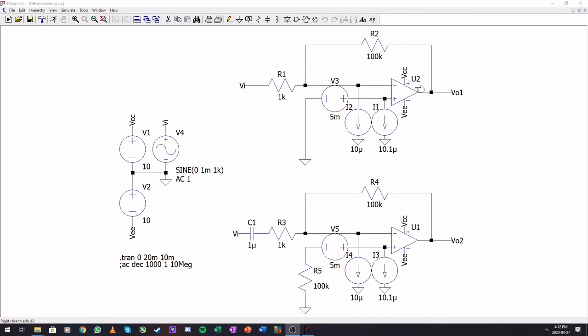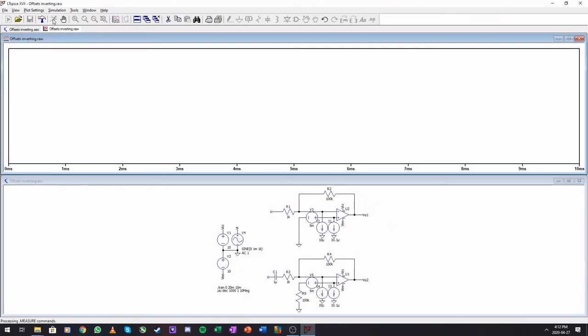Here I set up an ideal amplifier with an offset voltage and two bias currents with an offset between them. In the simulation we can have a look at both, and in here we countered firstly for the DC offset voltage, so there's only 5 millivolts being added here and 10 millivolts extra for our bias current counter of this resistor. So you need to add both the cap and the resistor to counter for the huge offsets that you can have. Let's run this.